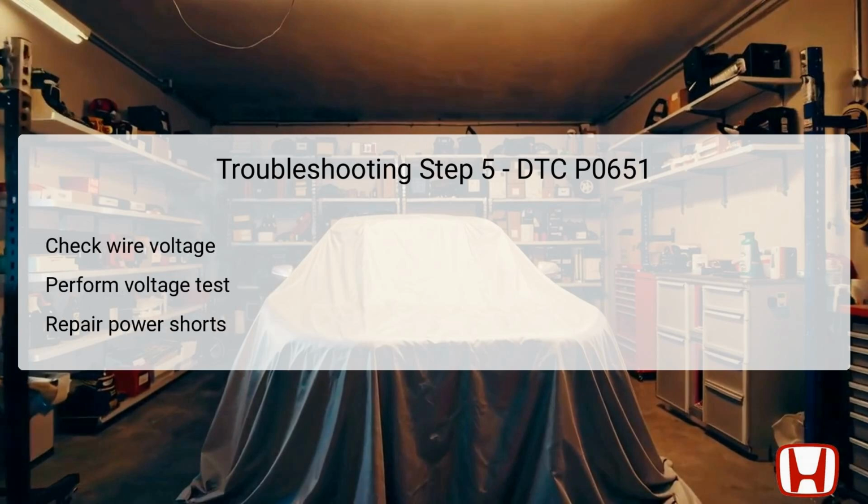The final troubleshooting step focuses on checking for shorts in the VCC lines leading to power. Start by turning the vehicle to the on mode, ensuring that electrical systems are powered. With the connectors for the CVT speed sensor, torque converter turbine speed sensor, and TCM still disconnected, measure the voltage between the specified test points and body ground.